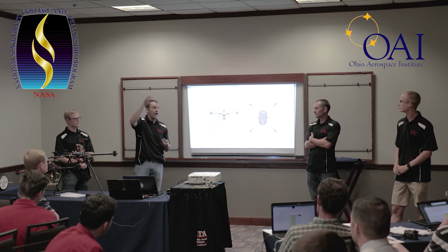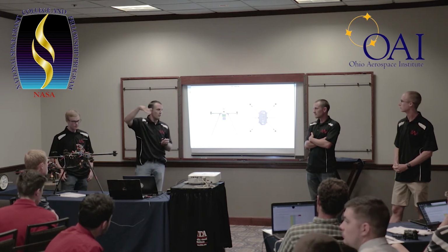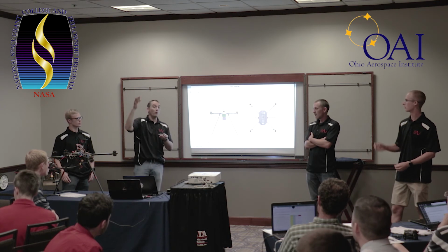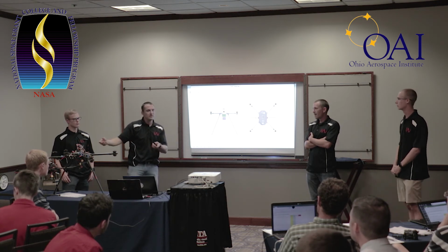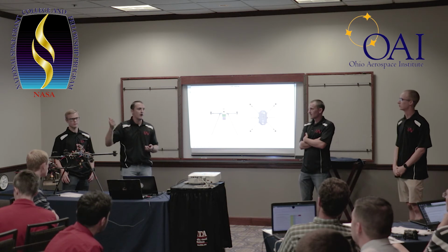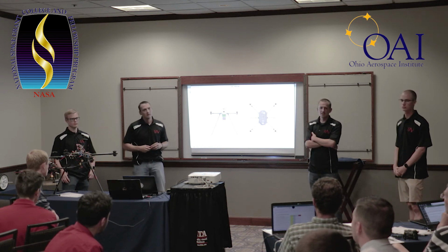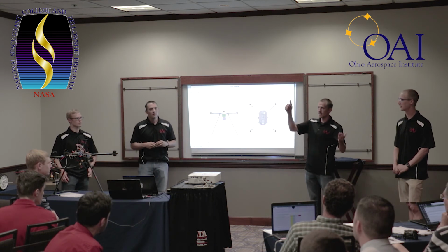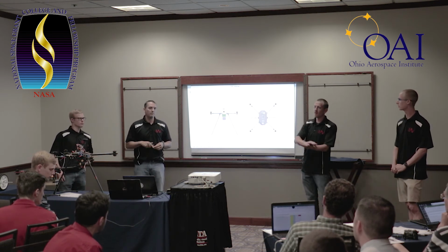It'll still be outputting to the motor that's dead because it doesn't know anything about that. It just says, send faster. But what you'll see is the other motors will be at a higher rate than you'd see in a traditional setup. To be clear, it's PX4, not PX. The one that's dead goes to max, and then the one underneath it raises above all the other bottom ones.